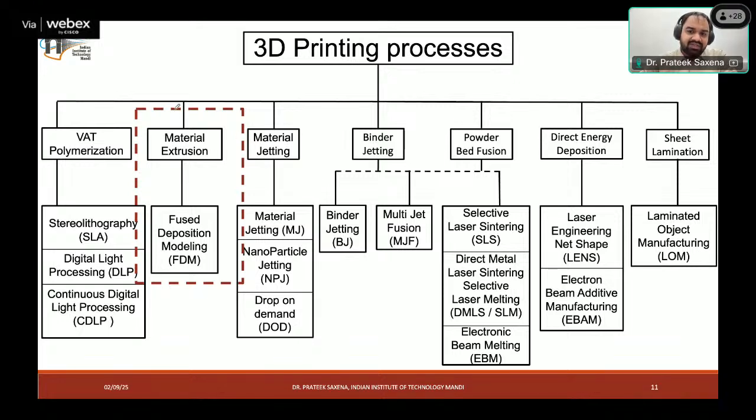Okay. So now we will come to the point: is it possible to 3D print your metal part using FDM printing or not? That will be the crux of our discussion in the next slides. Because this is a technique which I might have seen and experienced in my lab. The printers are also not very expensive. Printers start at something like 15,000 these days, 20,000. Some DIY kits are also there. So FDM is one thing which all must have experienced, but the problem is that FDM is used for thermoplastic materials and not for metals as of today.